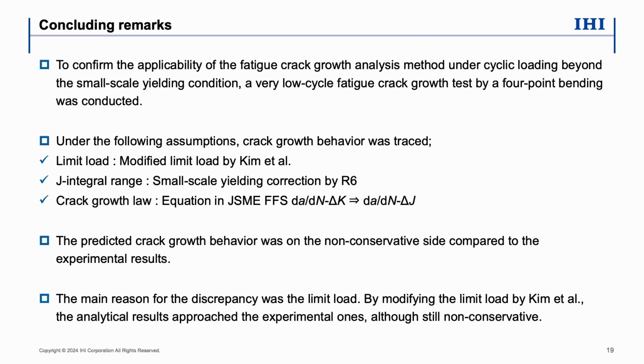Under these conditions, crack growth behavior was traced, and the predicted crack growth behavior was on the non-conservative side compared to the experimental result. The main reason for the discrepancy was the limit load. By modifying the limit load per Professor Kim et al., the analytical result approaches the experimental ones, although non-conservatism still remained.